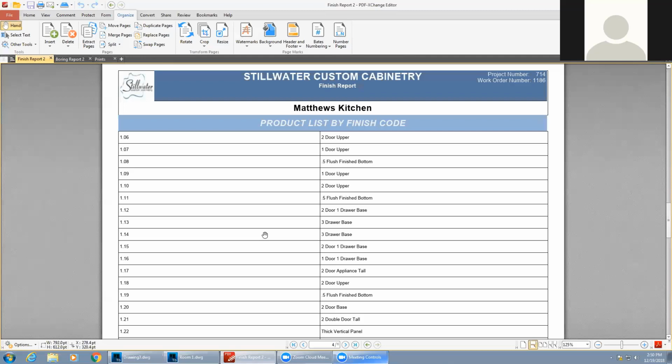It uses an Excel structure, but when you're referencing the material file for a specific part thickness to make this change parametric, you have to understand those aren't normal Excel formulas, okay, if that makes sense. You have to understand inside of Microvellum what you actually want to reference in order to get the results out that you're shooting for. But the basic structure of Microsoft Excel formulas is very alive and well, yes.